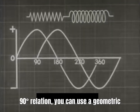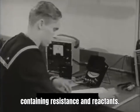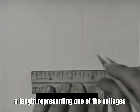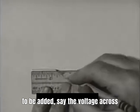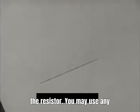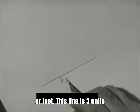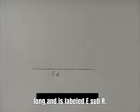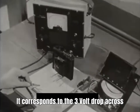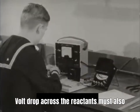Because of this 90-degree relation, you can use a geometric method of adding voltages in a circuit containing resistance and reactance. First, draw a straight horizontal line of a length representing one of the voltages to be added, say the voltage across the resistor. You may use any unit of measurement, centimeters, inches, or feet. This line is 3 units long and is labeled E sub R. It corresponds to the 3-volt drop across the resistor. The 4-volt drop across the reactance must also be considered.